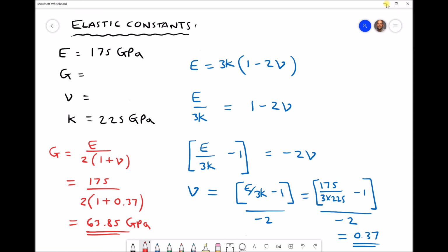We have the elastic modulus, which relates specifically to tensile and compressive forces. We have the modulus of rigidity, which relates to shear. And we have our bulk modulus, which relates to uniform pressure being applied to an object. But what we see is that the way the material responds in relation to each of these forces is actually connected. Now, in the next video, we're going to explore the Poisson's ratio a little bit more and see how materials respond to axial loads in the opposing directions.